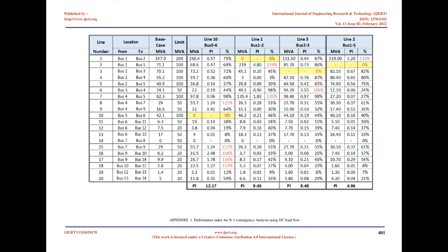Following the implementation of the QV curve analysis for the critical buses, I chose the top 4 critical line contingencies and noticed the voltage tolerance in the operating zone, as well as the sensitivity factor, dQ/dV, which tells us the allowable modification in the reactive power injection for the available voltage variance, as represented below in table 8.